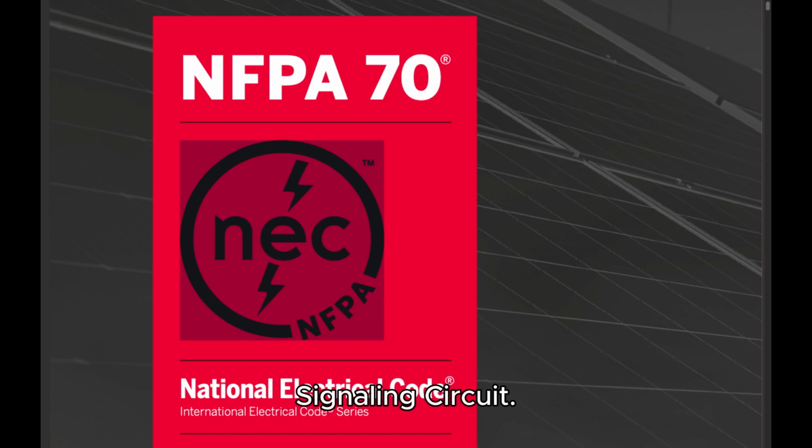CMP2 signaling circuit. Any electrical circuit that energizes signaling equipment. CMP3 simple apparatus, as applied to hazardous classified locations. An electrical component or combination of components of simple construction with well-defined electrical parameters that does not generate more than 1.5 volts, 100 milliamperes, and 25 milliwatts, or a passive component that does not dissipate more than 1.3 watts and is compatible with the intrinsic safety of the circuit in which it is used.